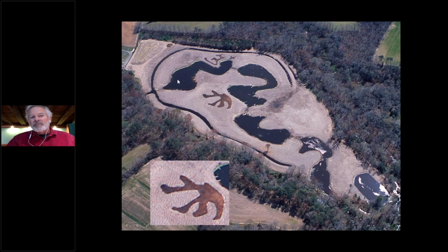It daylights into these surface ponds, which are connected by another riffle grade control, which sets the elevation so that this hyporheic process can't just run too fast. That way we have the contact time to get the kind of denitrification that we're looking at. As the water flows through this system, it ends up being returned to the stream from which it came before it flows into the swamp system.